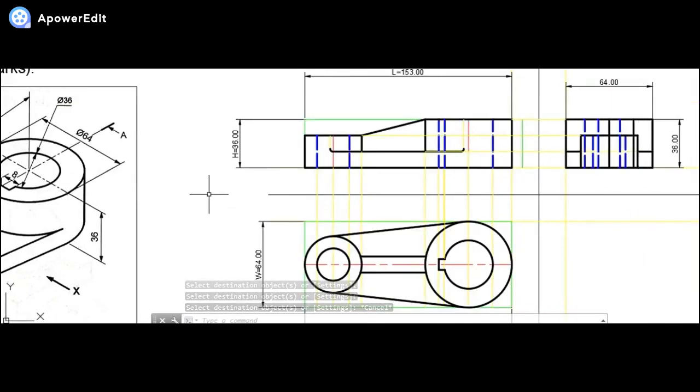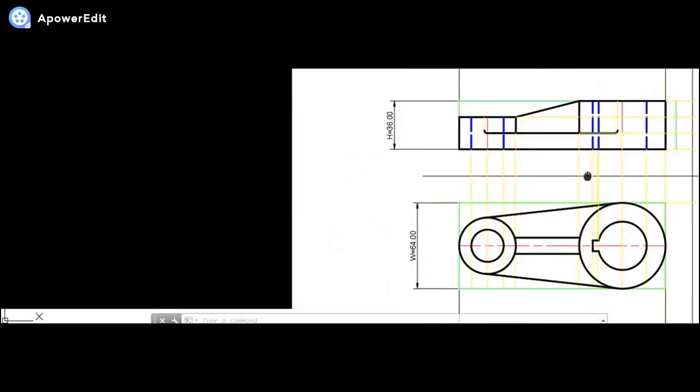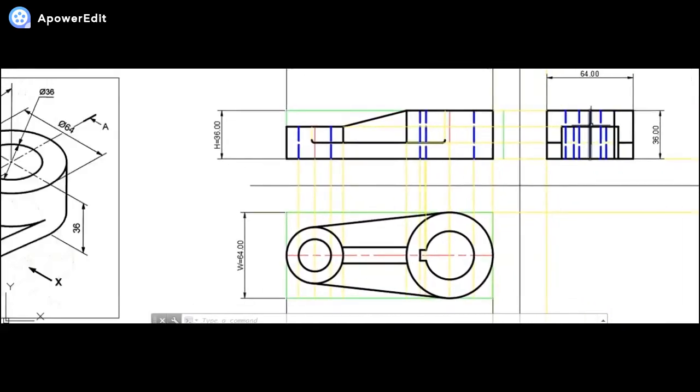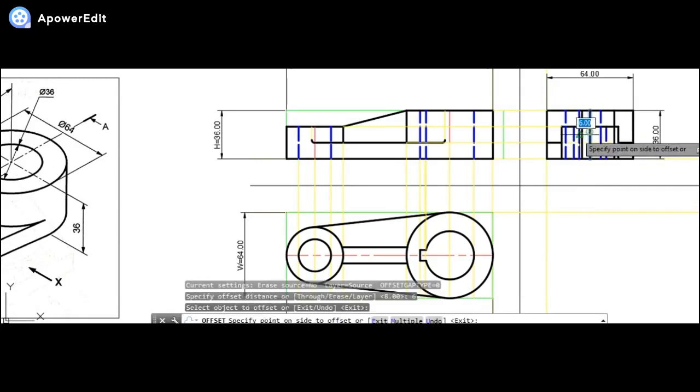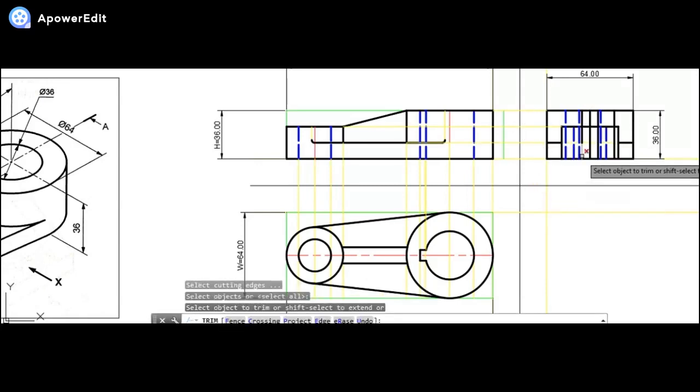So if I see about the rib, what happens? It is of 12 mm width. So now on this, from the center line on both the sides, 6 mm line we are going to draw. So over here 6, even over here 6. Okay. As you can see, it will be visible only above the upper cylinder. So the bottom part I am going to simply delete it or trim it. That is what I am doing about the rib.